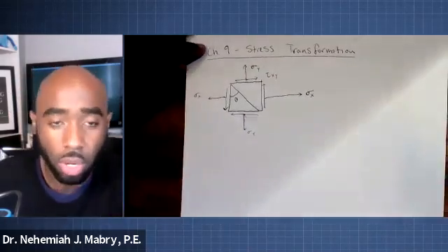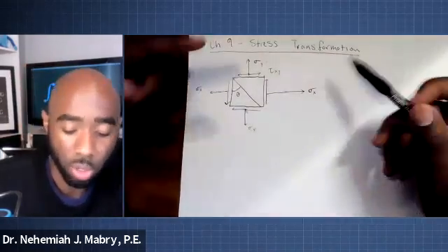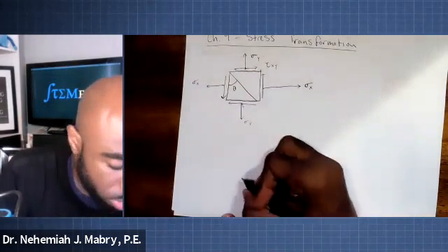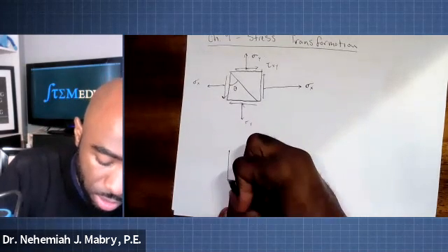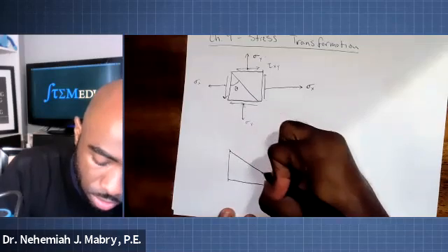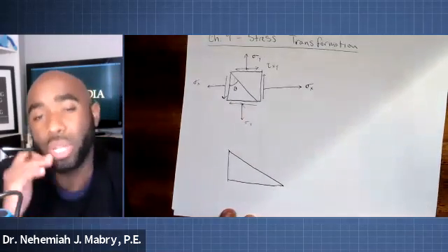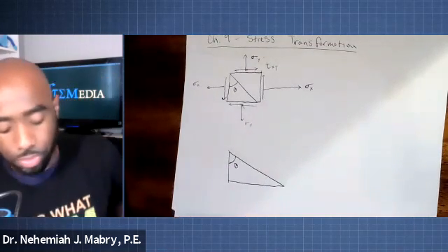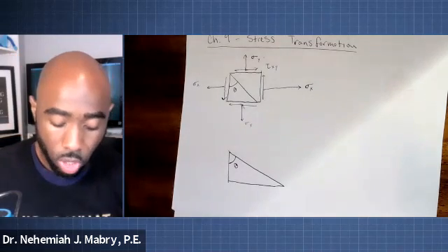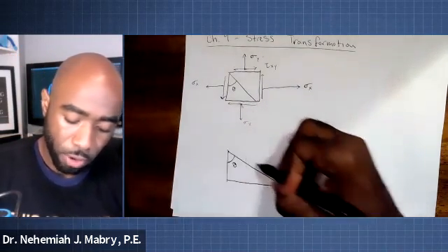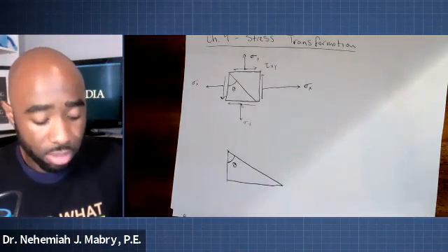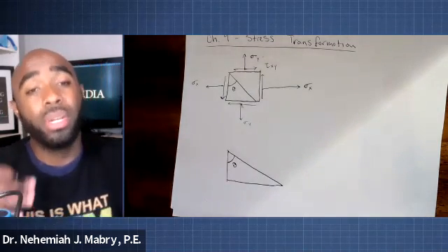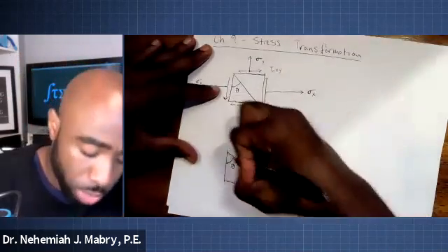Now, moving forward, one of the ways this is analyzed, when we see the angle, our normal and our shear stress, is by drawing a little triangle, which again illustrates the orientation of the stress plane. So this triangle will have an angle theta here, right? And we're going to treat this surface here, this hypotenuse surface, as the new plane, or the new orientation for which the maximum normal and shear stress occurs.